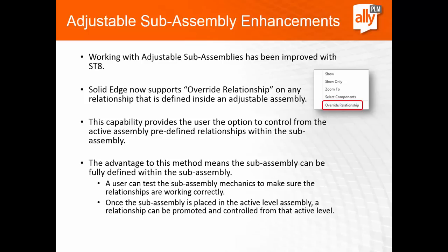Now in ST8 they added some new enhancements to work with adjustable subassemblies. There's a new option that now supports override relationships on any relationships that is defined inside of an adjustable assembly. So this is going to give you the option to control from your active level assembly any predefined relationships within your subassembly.